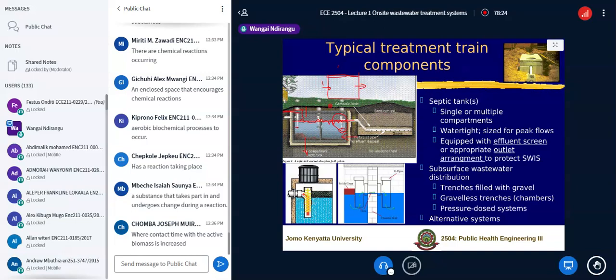Now, what do you think this water will do? The water approximately spreads at 45 degrees. So the water comes in there and spreads like that. But by the time it gets here, this is the outlet point, so the water needs to go out. So it starts converging towards the outlet.